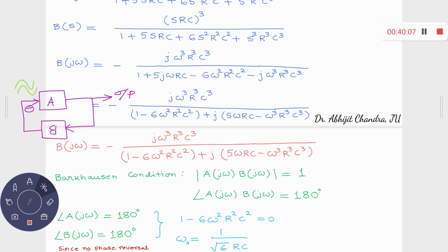But in our case, we have assumed that Lβ is equal to -1. Why -1? Why is there a 180 degree phase difference? Because we know that implicitly the amplifier itself provides a 180 degree phase difference. So that's why -1, because implicitly we assume that it's a negative feedback. So from here to here you understand that there is a negative part. That's why we have considered that Lβ is equal to -1.